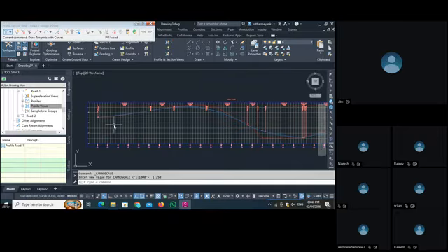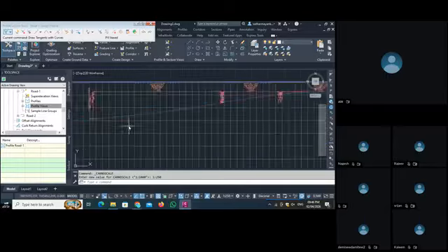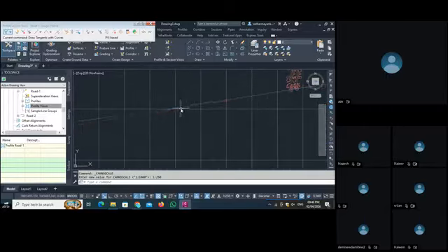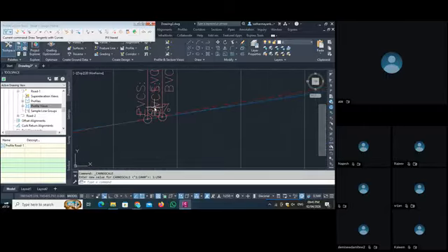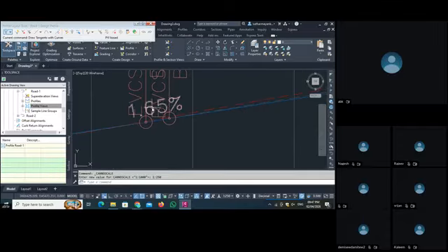Sometimes people will go to +5 or -5. More than +5 gradient and more than -5 gradient we avoid every time. The lower your gradient is, the more manageable your cutting and filling and your road is. See, I will show you all my gradients. So we have these first PI points, and you see our first gradient is 1.65.